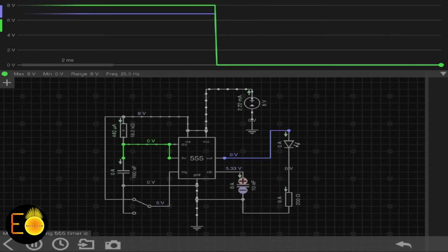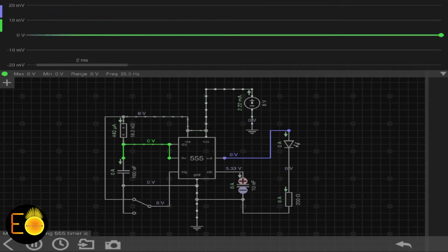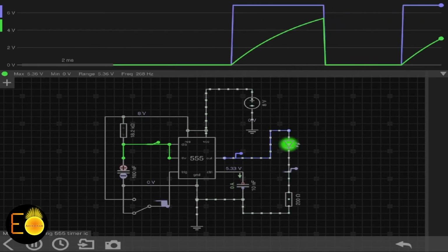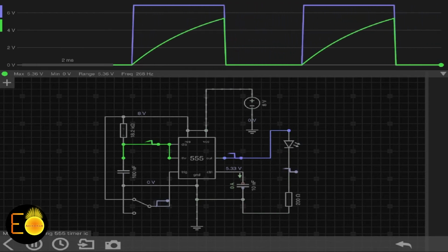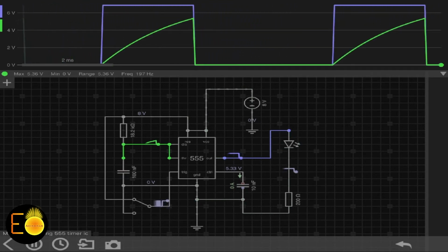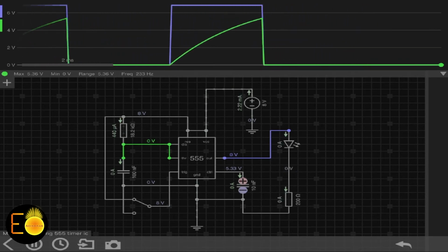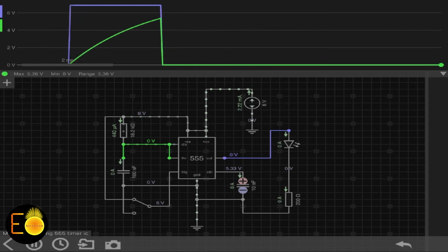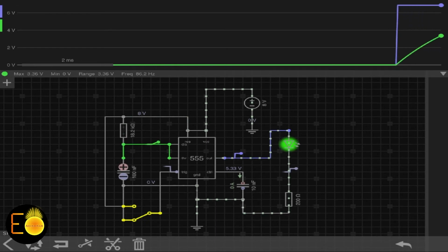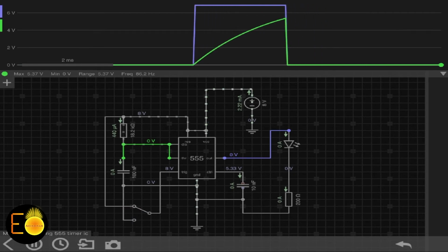And look, another interesting thing is that during the time when the output stays at its quasi-stable state, it doesn't matter how many times you apply the trigger. Look here, however many times I apply the trigger, it doesn't matter, the output state is not going to change. I'm changing the trigger multiple times. Okay, so once it gets triggered, the output is not going to change. But as I told, in order to apply the trigger further, you must reconnect it with the VCC. Otherwise, your next circuit will not work.